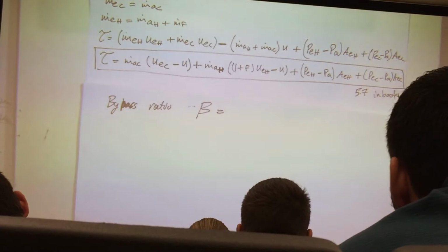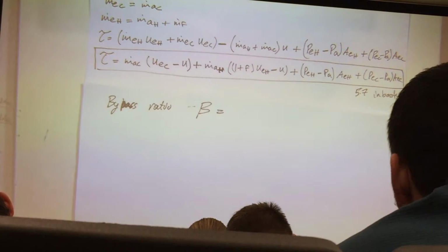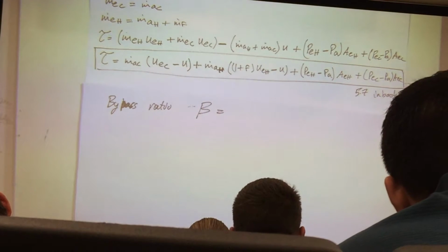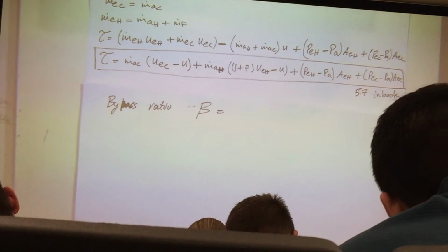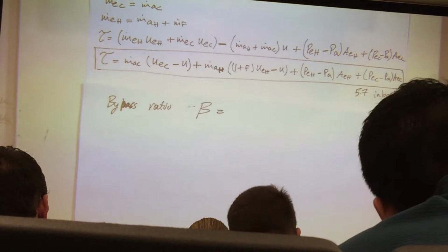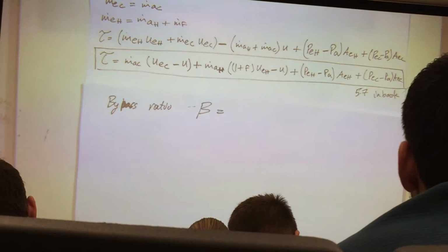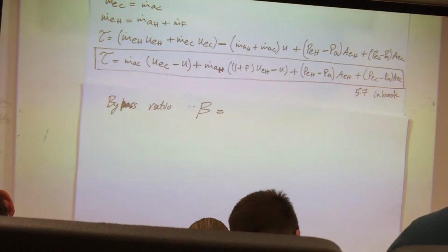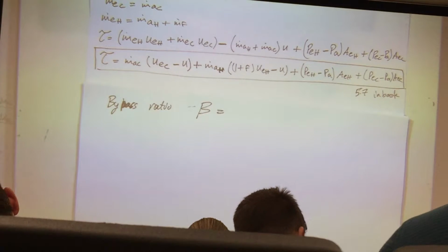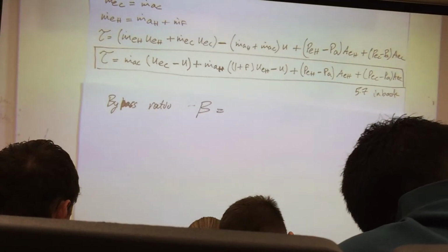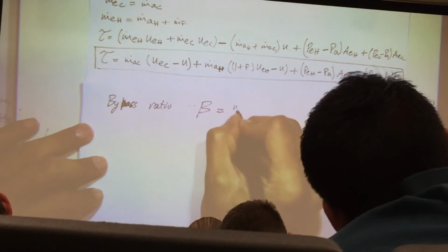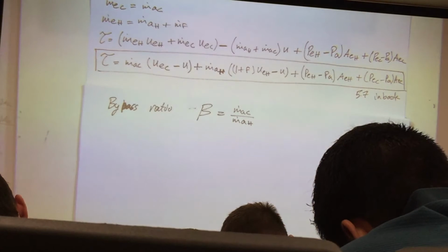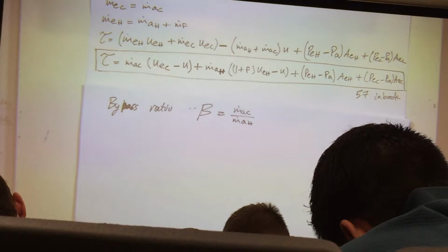And as I mentioned earlier, most of your thrust for your commercial engine comes actually from that fan. The engine is just primarily spooling the percentages, and you're going to play around with these later on and see how much thrust you're producing from the core versus the bypass. And depending on our bypass ratio, well, we'll talk about it when we get to turbofan. But the bypass ratio controls the mass ratio, which is cold relative to hot. Now, what does that mean? It means how much mass am I really?